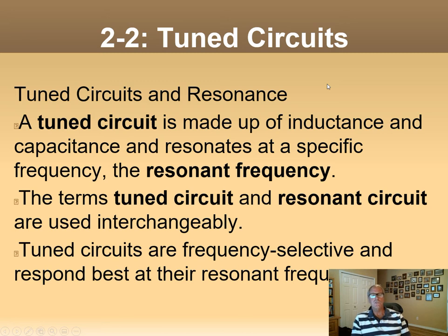Okay, let's look at tuned circuits. Tuned circuits, this is our lab this week, basically. Tuned circuits are made up of inductors and capacitors that resonate. The resonant frequency is when the inductive reactance and the capacitive reactance are the same. So there's some magical frequency, that resonant frequency, where the inductive reactance equals the capacitive reactance. That's the key, right?